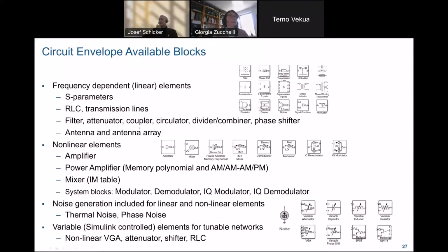You have linear elements, or elements that you can specify in the frequency domain, such as S parameters, transmission lines, lumped components, RLCs, filters, attenuators, couplers, circulators, dividers, phase shifters, antennas. These are all linear time invariant. We have nonlinear components, amplifiers, power amplifiers, mixers, as well as system blocks, entire subsystems like modulator, demodulator with I and Q components, including channel select and image reject filters, for example.